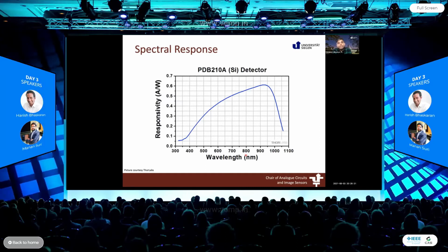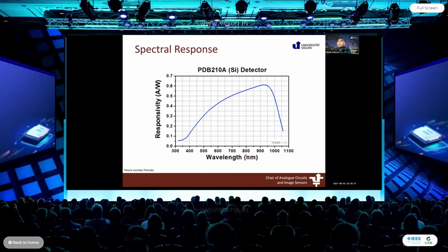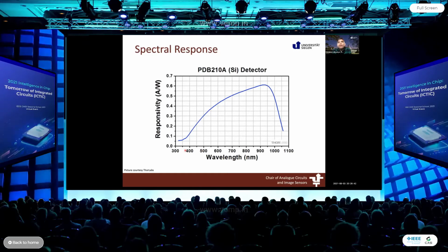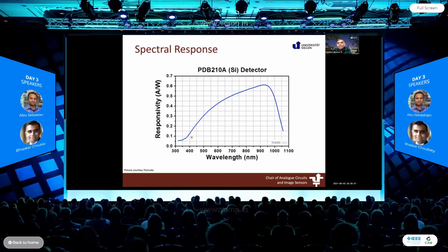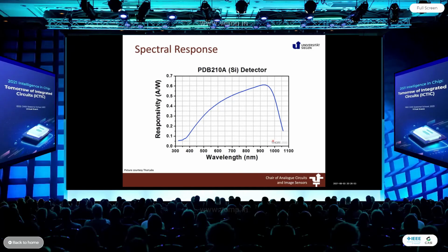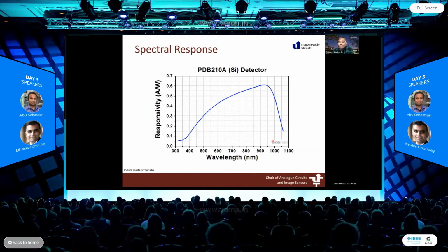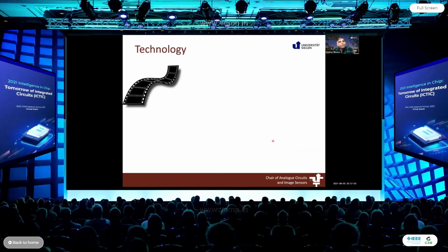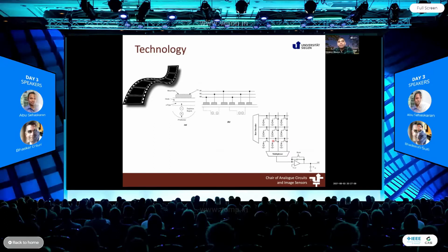Fortunately for us, the material used for making most circuits or most processing elements is silicon, whose optical sensitivity very nicely maps to that of the human eye. This is a spectral response of a typical silicon detector. It goes from about 400 to 900 nanometer of wavelength, which is also the blue to red wavelength to which our human eye is sensitive. So we have got a good base to start with. So it was easier for us to move from film-based technology to various pixel-based technology.